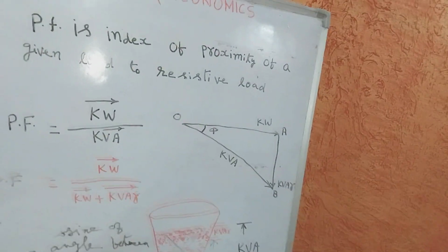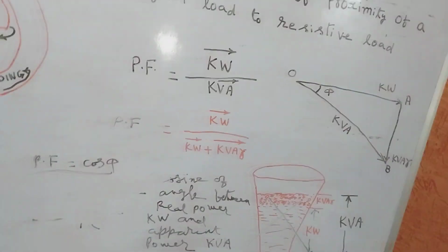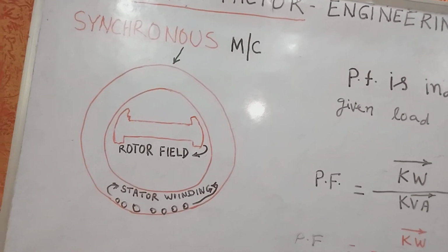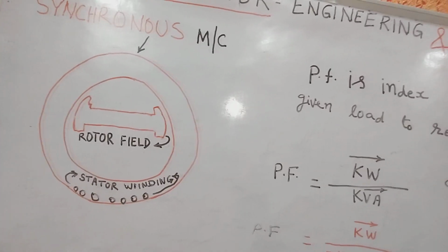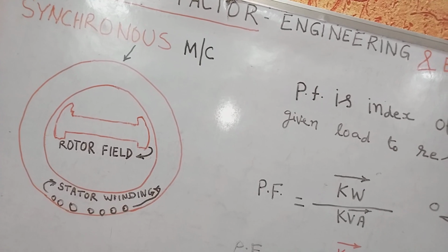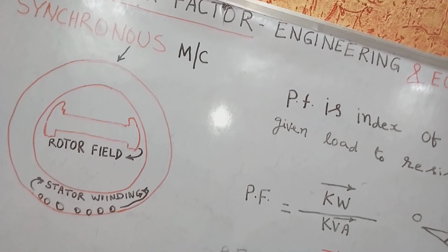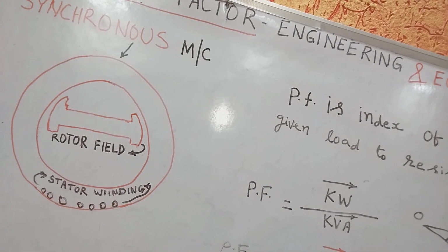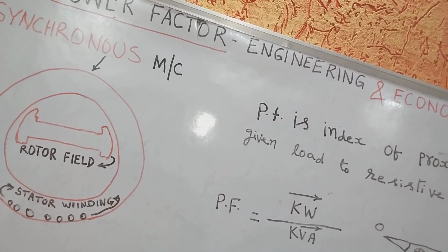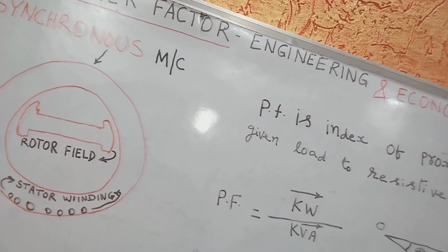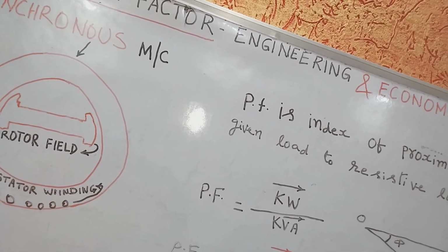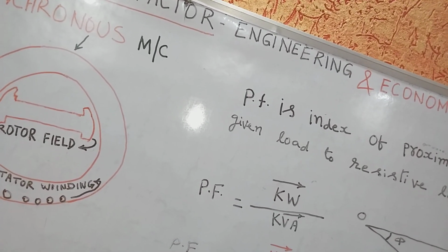Power factor can be corrected with the help of either condensers or capacitors, or synchronous motors or synchronous machines known as synchronous condensers. With synchronous motors, there are two possible sources of excitation: alternating current in the armature or direct current in the field winding. If the field current is just sufficient to supply the necessary MMF, no magnetizing current component or reactive kVA is needed in the armature, and the motor operates at unity power factor.